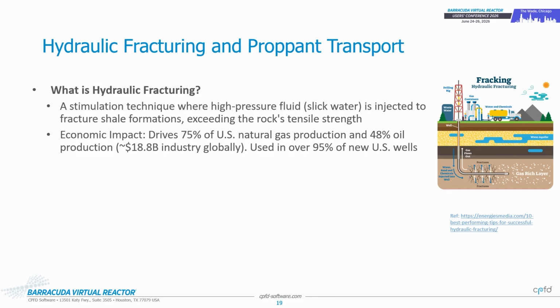Apparently not, right? Because you have got hundreds of feet of earth on top of it. So how do you keep these fractures open? You pump in proppants. Proppants are literally solid particles. They could be as simple as sand. They could be highly customized coated material as well. So essentially a whole bunch of solids that you're pumping in. You're hoping that all these solids settle down in these fractures. It's literally a filling problem. You're hoping it fills as far as it can, as much as it can. So you prop open these fractures and you produce oil from them.